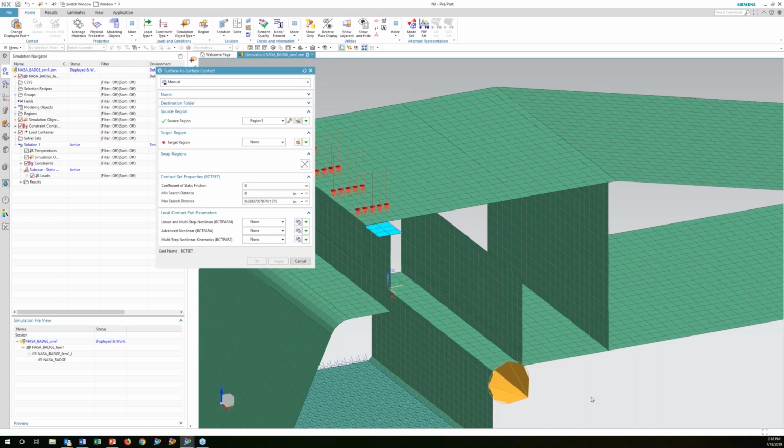So that sort of does exist in FEMAP. There is, under modify, update elements, adjust mid-surface thickness and offset, which will be able to grab information from a mid-surface and map it to elements. And if you want, after the webinar, I can go ahead and show you. I have a nice example on that as well.